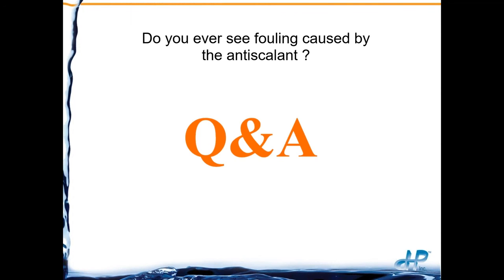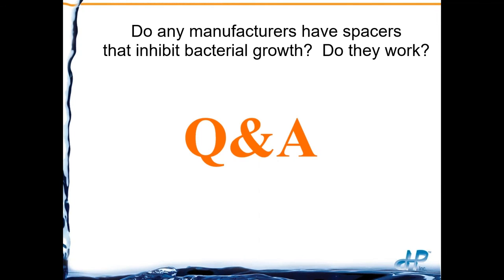The other thing, which we have run into a couple times in the last couple of years, is that you can have a cationic polymer injected in front of a clarifier or a media filter, something like that. That cationic polymer, as the name implies, is a positive charge. The antiscalant is going to be a negative charge. Not all cationic polymers and antiscalants will interact, but we have seen a couple times where they attract to each other and form this snotty mess and then lay out on the membrane itself. So it's a cationic polymer and scale inhibitor interaction that is actually plugging up the membrane in that case. But the antiscalant itself, we rarely see actually plugging up membranes.